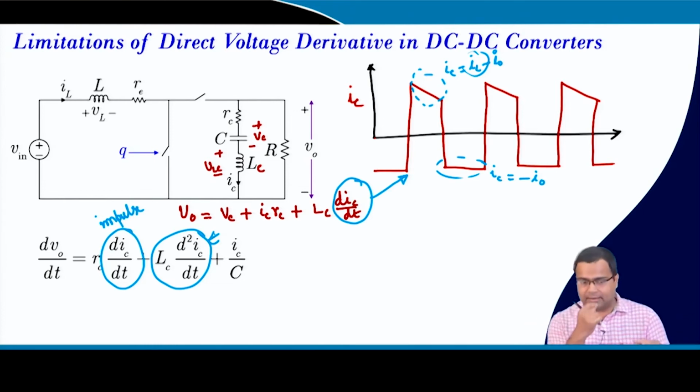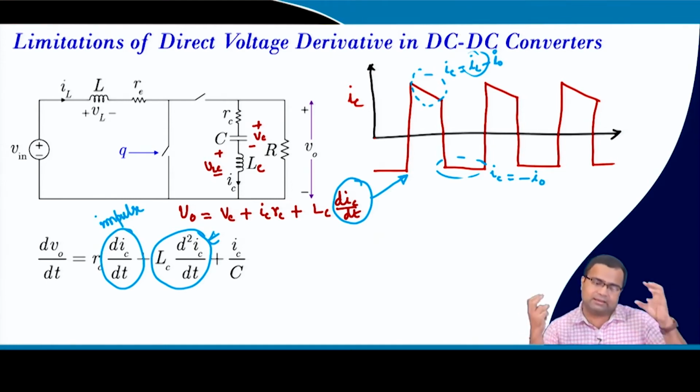Even if we take a practical PID controller with a band limited action, you still can, because what we are going to do, if we link this PID controller with a switching surface, then we can tune this PID controller using the switching surface point of view, not from the small signal model, and then we can take back the pure band limited derivative action.